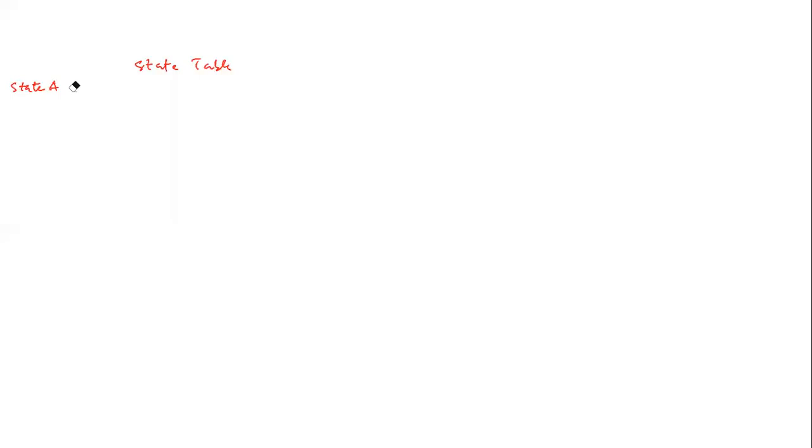Let's populate this table. Okay, so now we have this, but recall that we have 16 possible code words, and we already said code word per state. We have 3 registers, so it's 2 to the power of 3 minus 1, which is 4 states. So we have 4 code words per state. So we're able to have 4 states. And now it's a 7-step Trellis diagram.